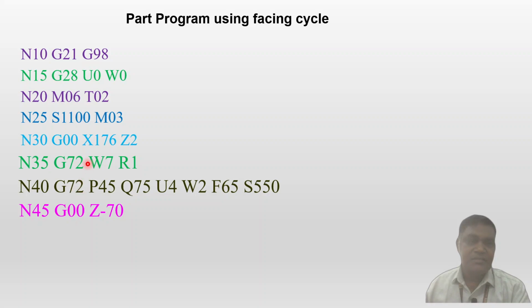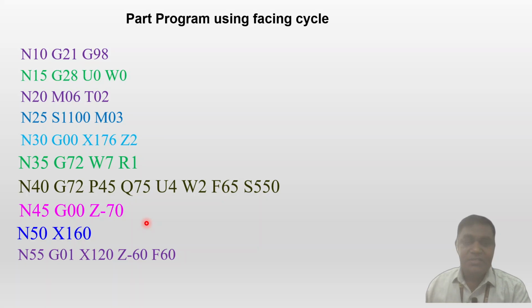Then after this, go for G00 Z-70, then X160, then G01 X120 Z-60 F60, and Z-50.